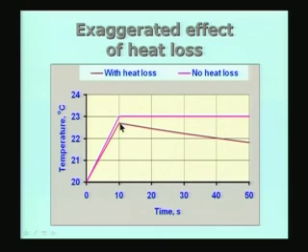Now if you look at the cooling process, this is again governed by the same cooling relationship: capital K into T minus T1 gives the derivative of temperature with respect to time. So, using this part of the process, I can find out capital K. Capital K is nothing but the first order time constant of that system, which is getting cooled down. And if I can get the value of K from the cooling curve, that can be used in the earlier expression.